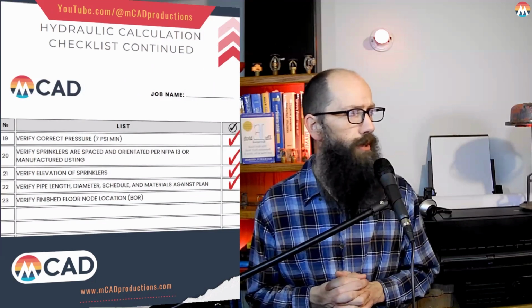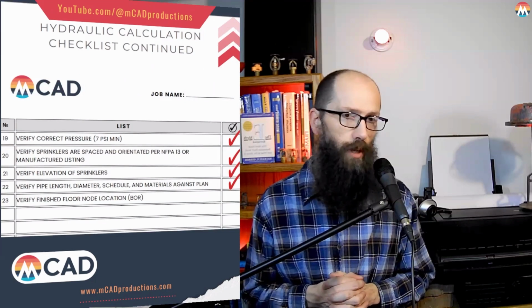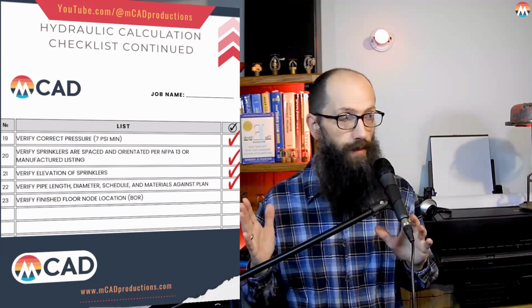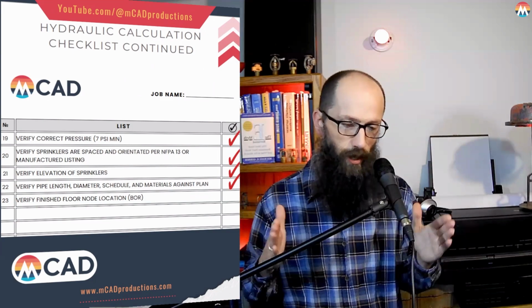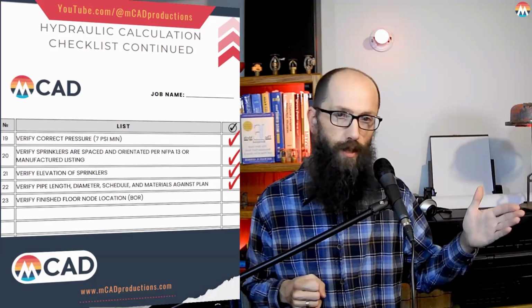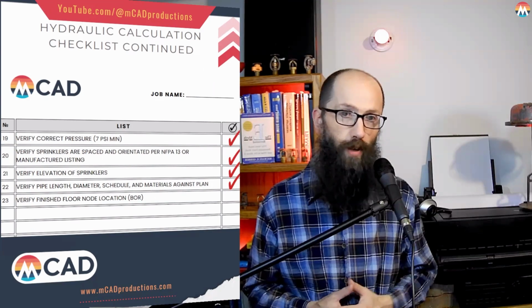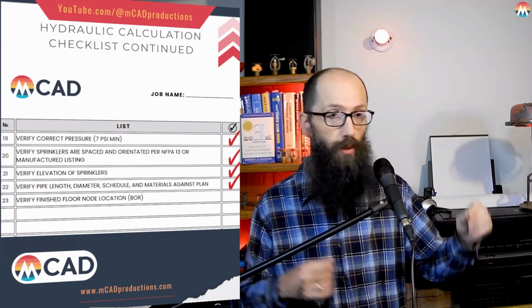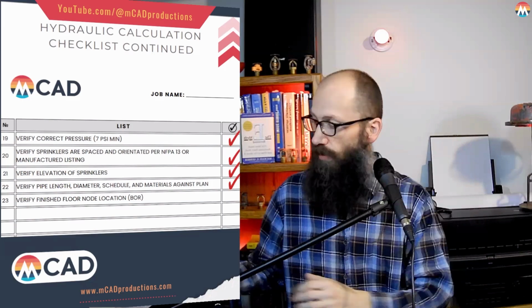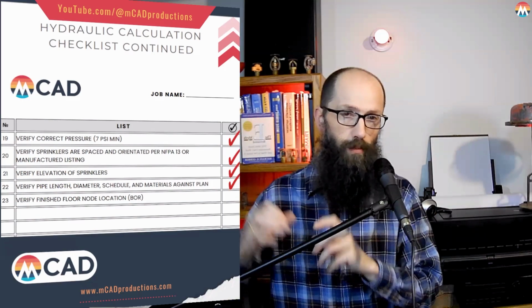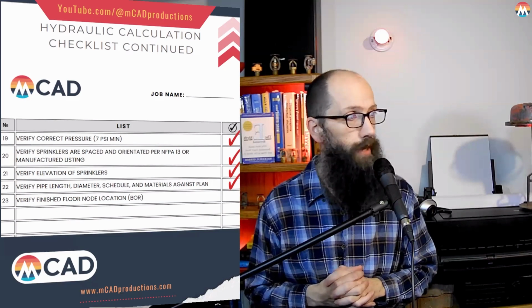All right, now the last thing to talk about, we check on the calcs. I want to mention, this was going through quickly. That last step, we would do for every single line. There were only 5 lines, I think, on this calc, so that's not too big a deal. But you might have 4 or 5 pages of lines to sort through, and we would just look at the line and compare it to the drawing. Does this add up? Do these lengths match? Does this diameter of pipe match? Does it look like they used the right type of pipe? Those are all the types of things we're looking at.